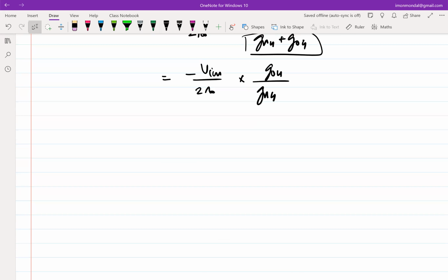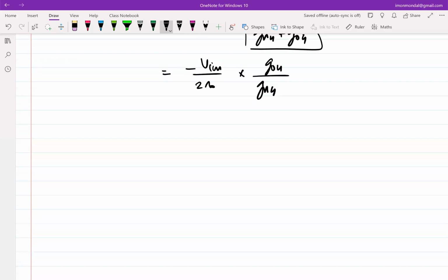So this differential amplifier structure works fairly well if you are looking for a gain of, let's say, 30 dB, 40 dB, and similar to that I gave in the project. But this differential amplifier works well if the load is capacitive. If the load is resistive, then you have a problem, because I'll show with respect to only the GM.